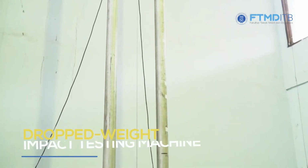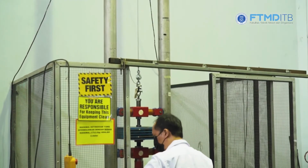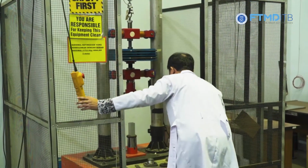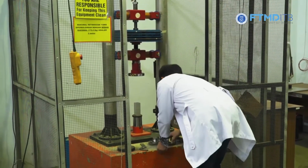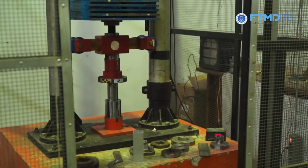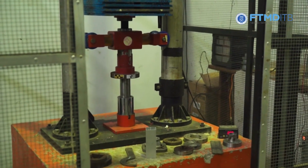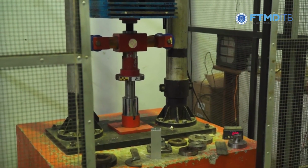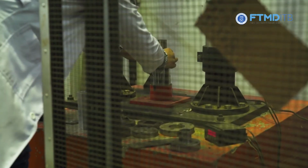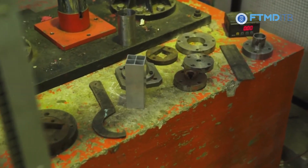Drop weight machine is a tool used to determine the strength of a structure when subjected to impact loads. In an impact test using this equipment, the specimen is placed and held at the bottom part of the equipment, and then an object or load will be pulled up above the specimen to a particular height, and then released. This load will fall down and hit the specimen to give an impact load to the specimen.